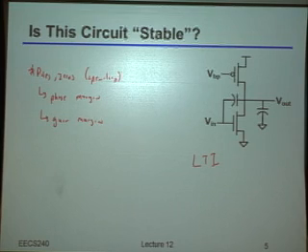Okay? Because if you think about it, let's say I changed the temperature, or the temperature changed due to, whatever, the sun or the moon getting closer, whatever it is. Well, the circuit would actually change its characteristics, right? So the take-home point here is that you have to be really careful when you talk about stability, because most of our notions of stability, most of the things we like to think about, particularly as circuit designers, are only true given that the circuit is actually linear time invariant.